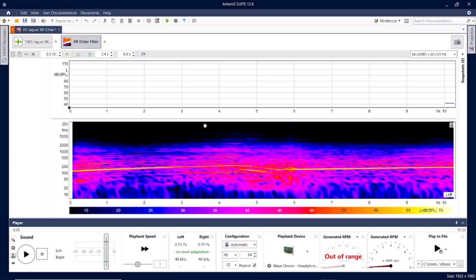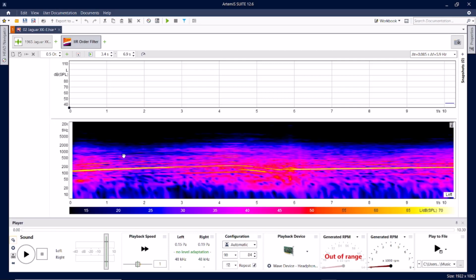This is an internet sound. It's not a calibrated sound. So anyway, we're going to get the IIR order filter, and there are two ways, by the way, to use it, but we're coming to that in a moment. The normal way is what I showed before, where you click in the spectrogram, hold control, you see the cursor, and you step at 1/2 order spaces. You can go to much finer resolution if you type the number in instead.